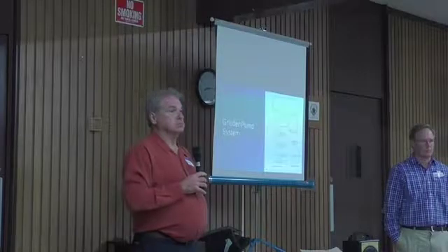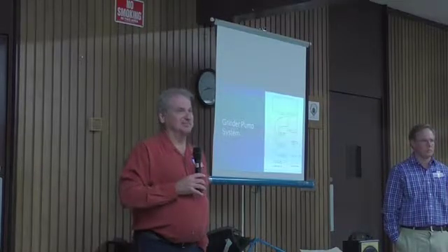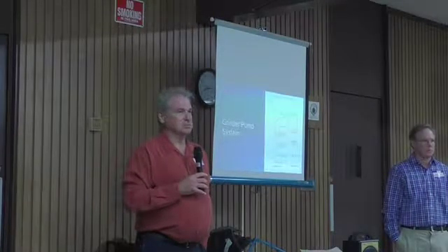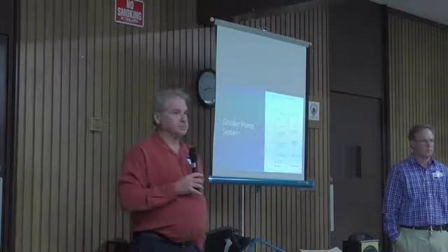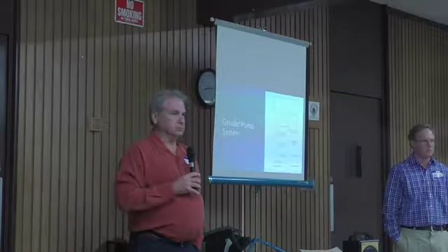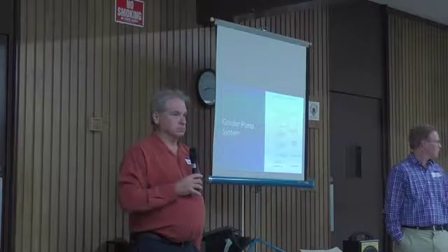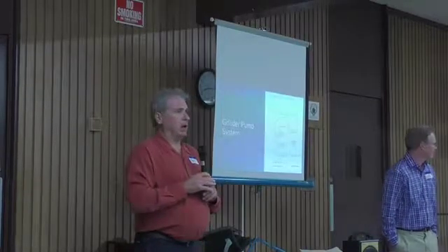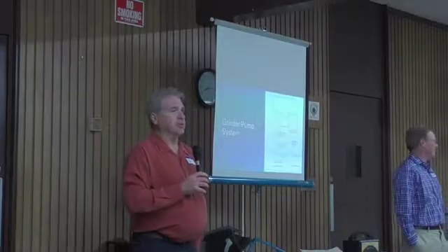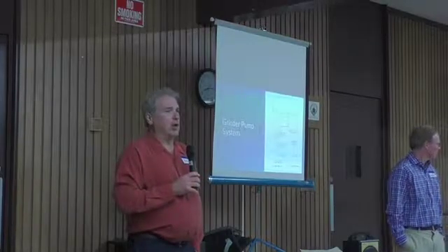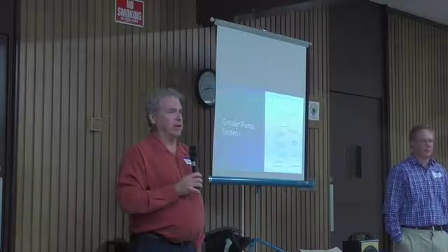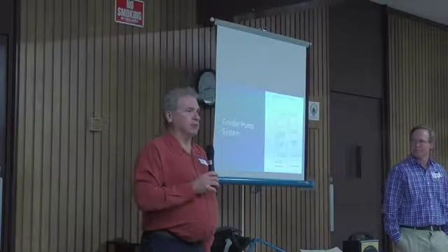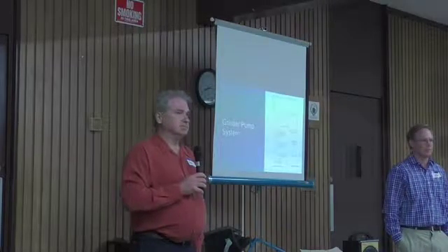But they may not be planning to add an air conditioner. Now they're mandated to add another 20 amp circuit that they may not have. And they have an old Zinsco panel, and now all of a sudden they've got to add a whole new breaker panel. It's not going to be perfect. I would hope that would be a very rare instance, that most houses have the capability of adding one more 30 amp circuit. We are economically depressed here.